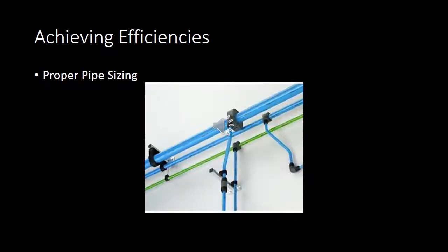Proper pipe sizing. Pipes must be sized correctly for optimal performance, or resized to fit the compressor system. Inadequate pipe sizing can cause pressure losses, increase leaks, and increase generating costs. Increasing the pipe diameter typically reduces the annual compressor energy consumption by 3%.